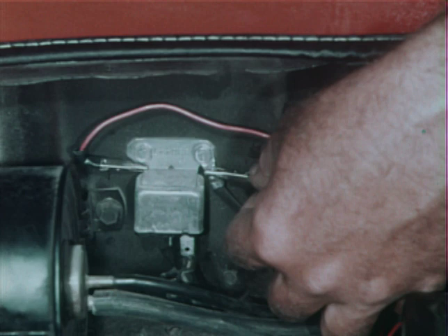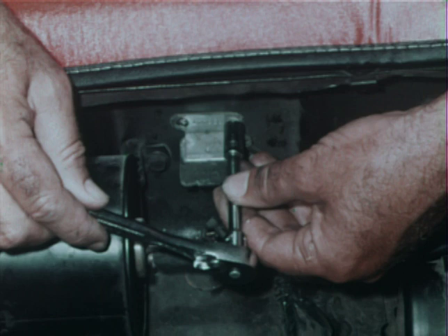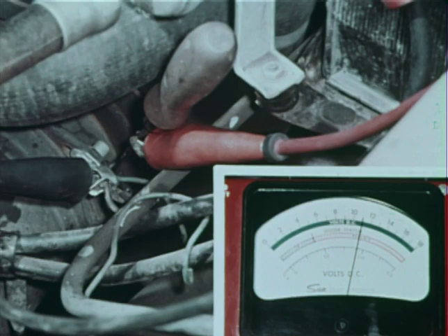If the compressor clutch engaged normally after 25 seconds, with the relay connector installed and with the jumper wire in place, the relay would have to be removed and the ground connection cleaned. If the compressor still chattered or slipped with the relay grounded and the connector in place, but engaged normally with the connector removed, the malfunctioning relay would have to be replaced. In this case, the compressor clutch still chatters or slips with the time delay relay disconnected.